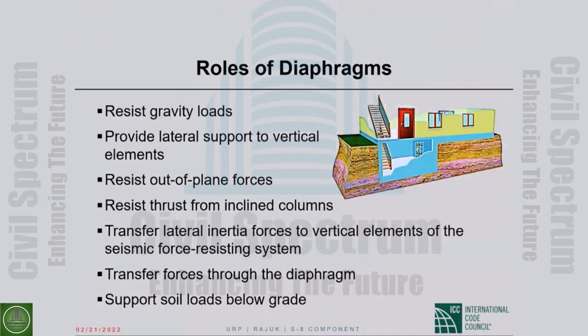Transfer lateral inertia forces to vertical elements of the seismic force resisting system. This is huge. This is a major role that diaphragms play. Transfer lateral inertia forces to vertical elements of the seismic force resisting system. Also transfer forces through the diaphragm, and if you go all the way down, support soil loads below grade.